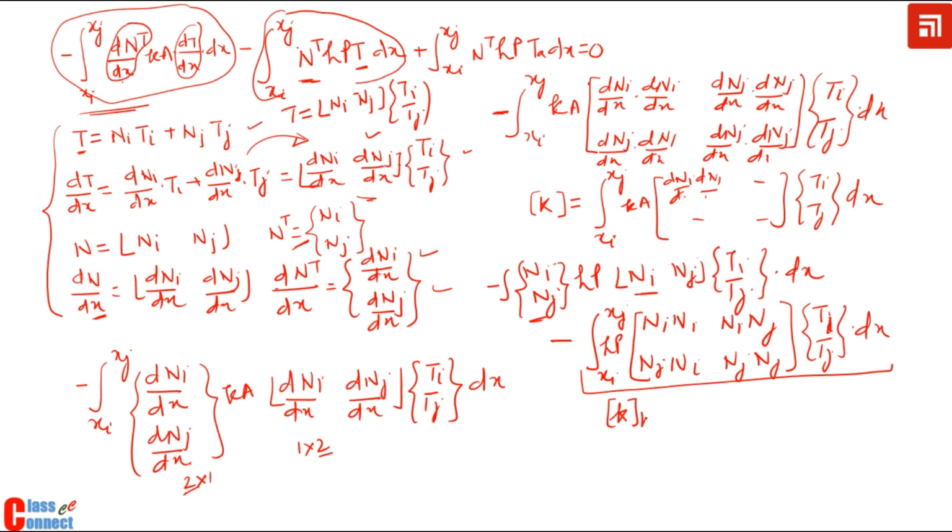So we generally write this with subscript H, representing a convective heat stiffness matrix or thermal stiffness matrix due to the convective component. Now I can make use of this. This is excluding this; this is not part of the stiffness matrix, and this is also not part of the stiffness matrix.